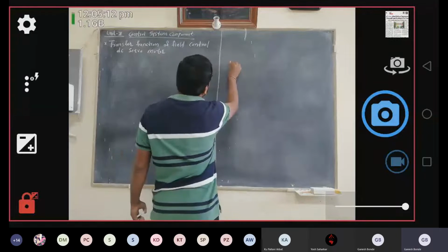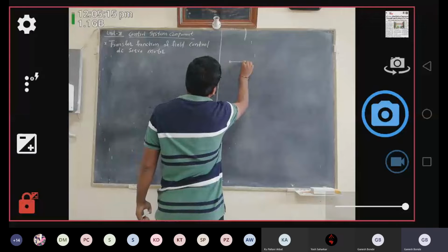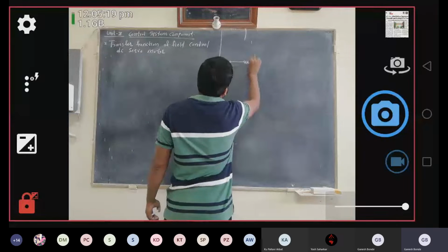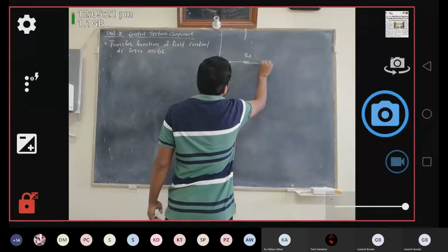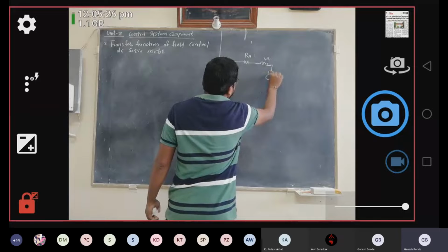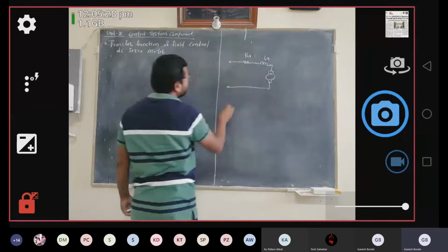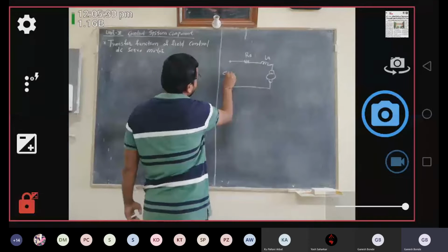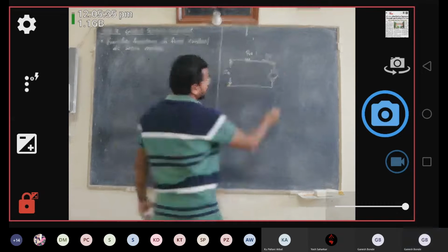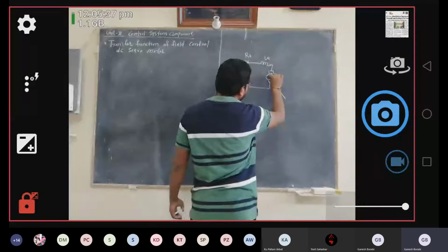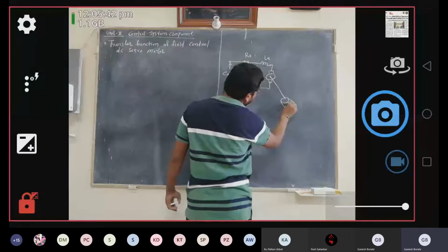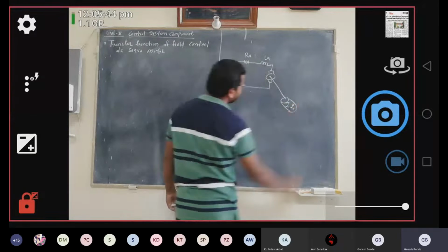DC servo motor. So first we have drawn an armature circuit, its equivalent circuit. So it has its own resistance RA, inductance LA, then armature. Okay, so this is your armature circuit, and input voltage applied to the armature is EA. Okay, then this is the shaft of your armature. So your armature has its own moment of inertia and frictional force F0.